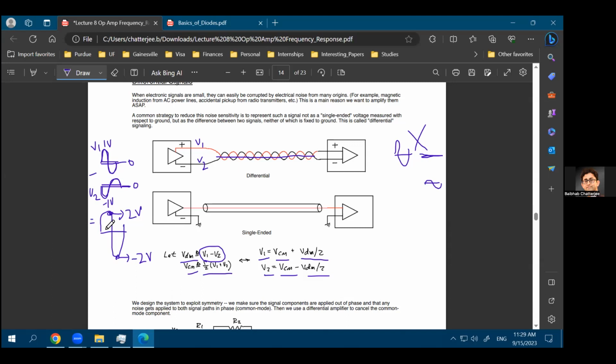So then, noise is a fairly common thing. Why would you ever use single-ended? Again, a great question. So differential takes double the amount of hardware, and it also takes more power consumption. So if you want to build a smaller system with lower power consumption, single-ended sometimes works if your signal levels are much higher than noise levels. So noise would be, let's say, microvolts to a few millivolts.